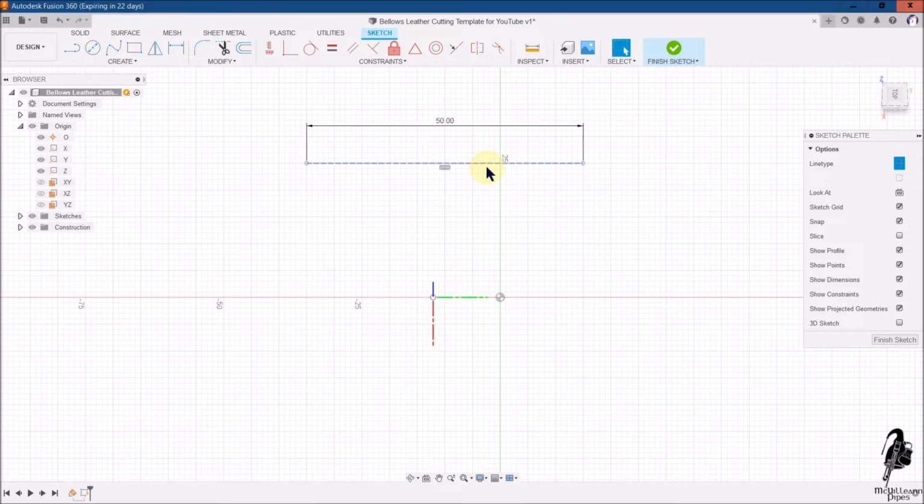Now, I create this line away from the origin here, because if you put it close to the origin, it can get very hard to find the center point of the line, which is what we want to do, and we want to make it coincident. So constraint coincident. Go hunt the center, shift key, hold the shift key down, find it around here. We found it and it went away. So shift key down, found it. We want it to be coincident with the main origin.